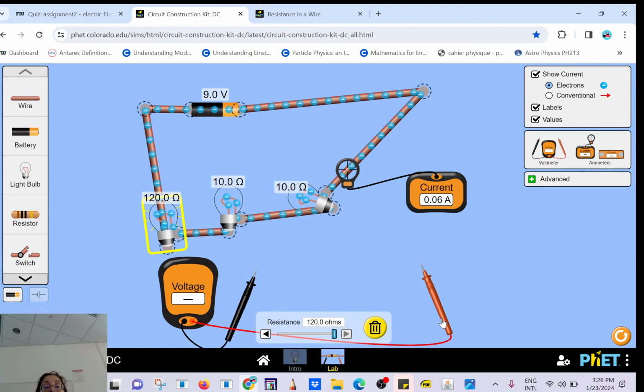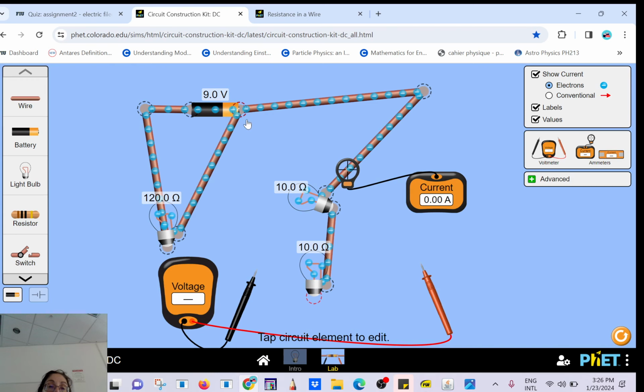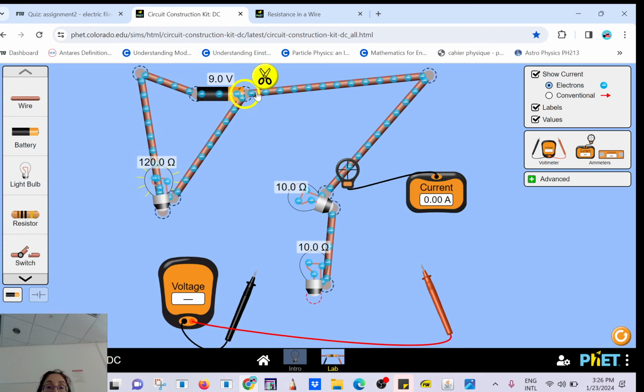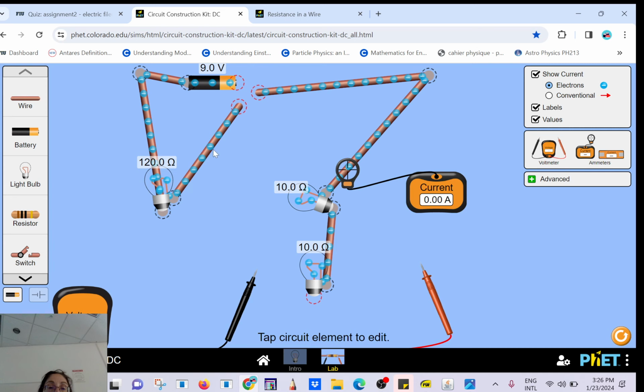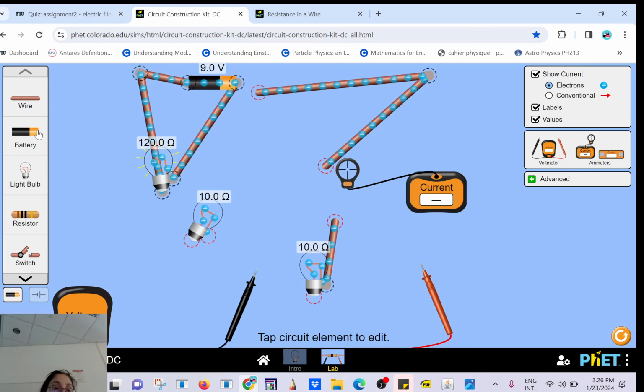Okay? So that will be very bad because in a house, if you have a microwave and then you have a lamp and then you have audio, one of them is not going to work. So we don't do it that way. So the way to do it is what's called a circuit in parallel. So each one, so this one is happy. And now I'm gonna add this one. Okay. He wants also to be connected to the battery.